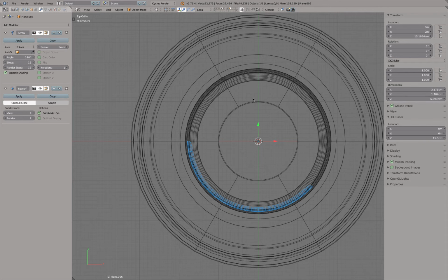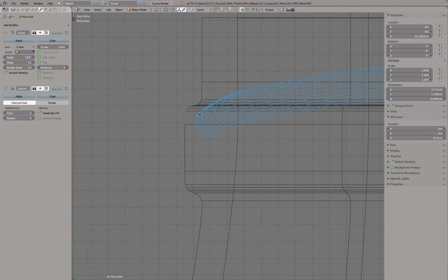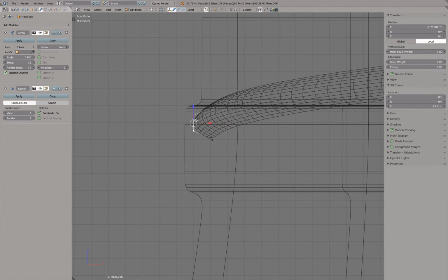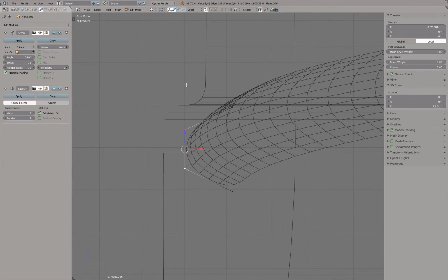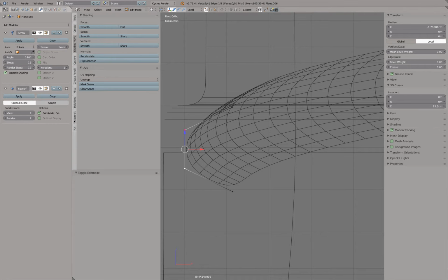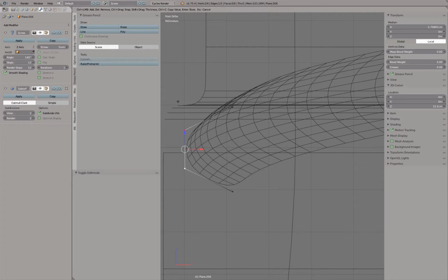So my threading is rotated not along the Y but the Z axis. So the end cap is actually lined up, not perpendicular to me. So I can better, for example, guess maybe the distance. So what is this distance? Let's measure it quickly. Let's go to measure, whoops, not this one, there. And then left mouse button click and drag and release left mouse button click. Okay, so 5 millimeters. So roughly this grid line is actually where my mesh at the end has to be.